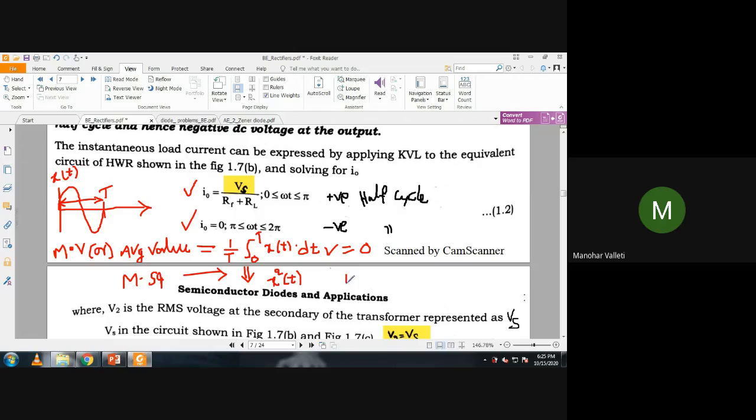The same way, for root mean square value, that is RMS, the same mean square formula will come, with the root. These are the usual mathematical definitions. So we will use these definitions to analyze my output waveform. Generally, the mean value or average value gives the DC value present in the waveform. How much DC is present in my waveform.